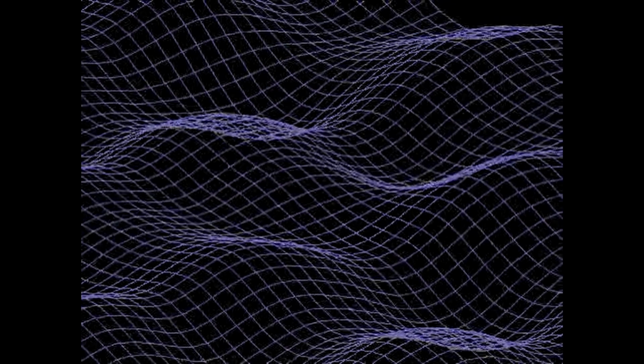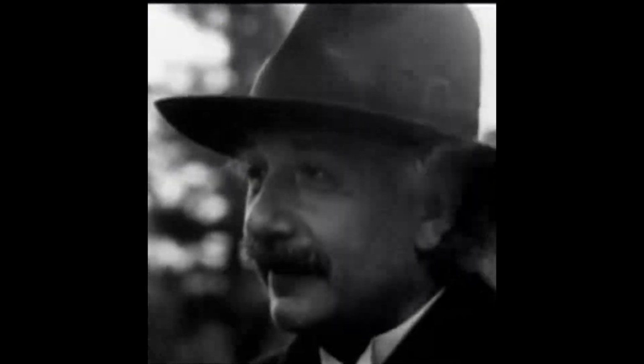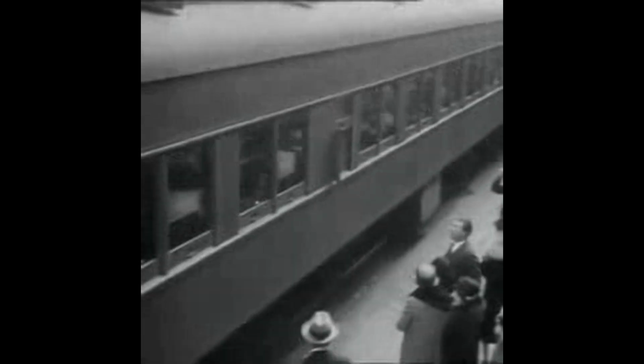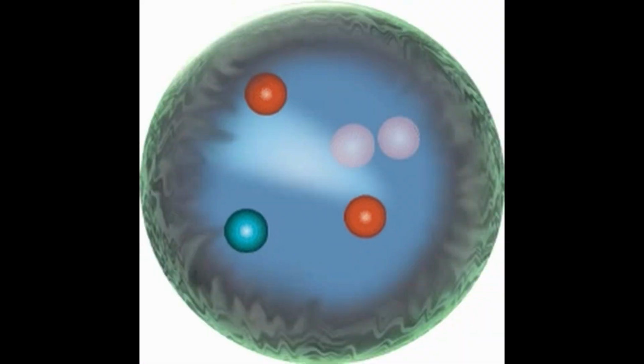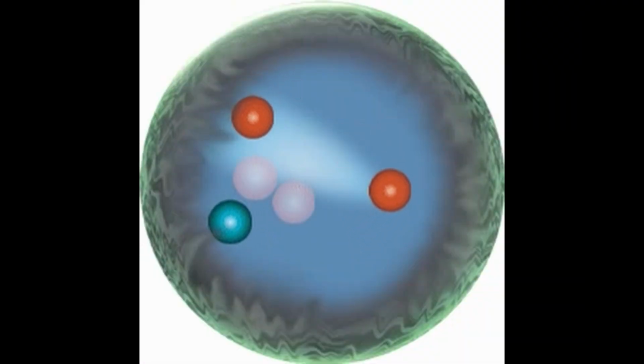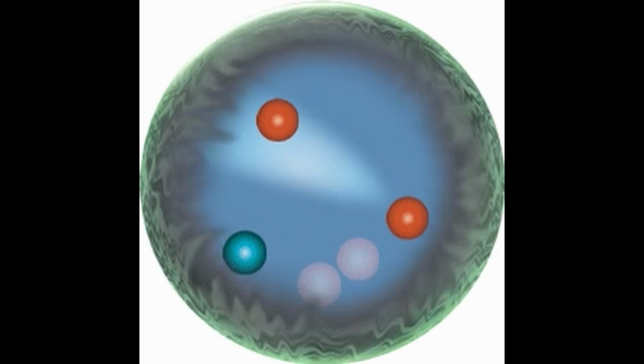Faraday's law is intrinsically connected to the concept of magnetic flux. Here's how they relate. Magnetic flux Φ is a measure of the total magnetic field B passing through a given area. It's calculated as the product of the magnetic field and the perpendicular area it penetrates: Φ equals BA cos θ, where θ is the angle between the magnetic field and the normal perpendicular to the area. Faraday's law states that a change in magnetic flux through a circuit induces an electromotive force, EMF, in the circuit. The law is mathematically expressed as EMF equals −dΦ/dt, where dΦ/dt is the rate of change of